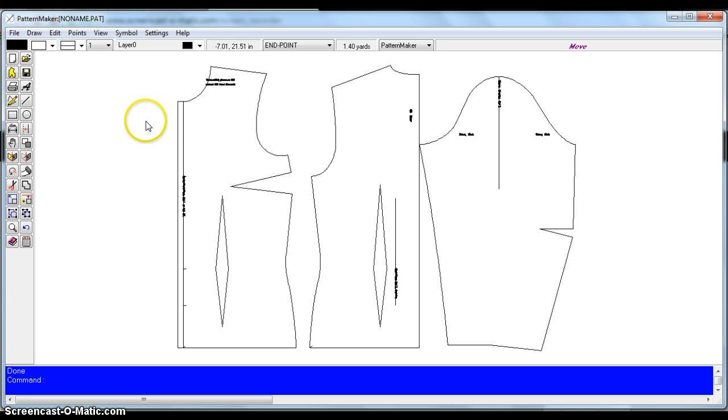And the lines look like they're overlapped right now, but we're going to join the rectangle to the rest of the front. We can take our snap off. You can do that by using your keyboard hotkeys. Control key F1 turns our snap off. There we go. It tells us right there, or we could change it there.